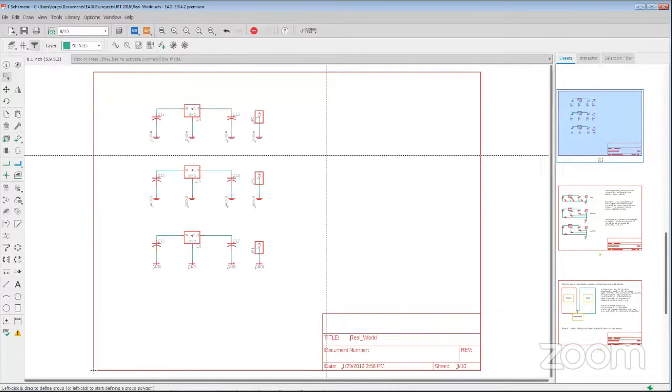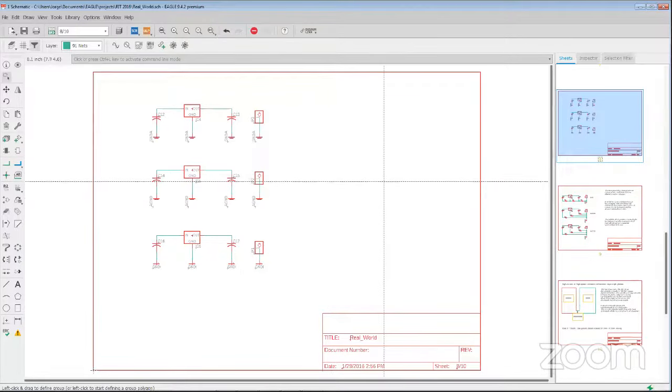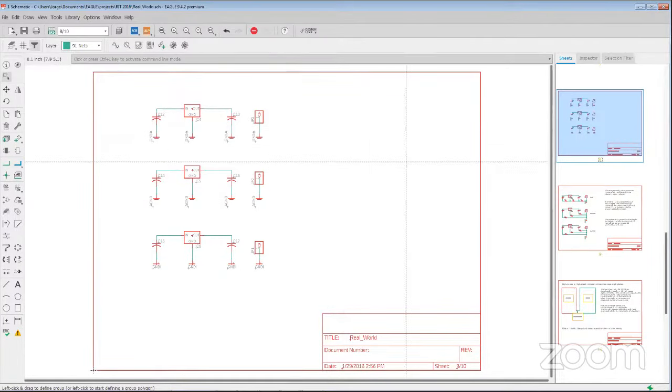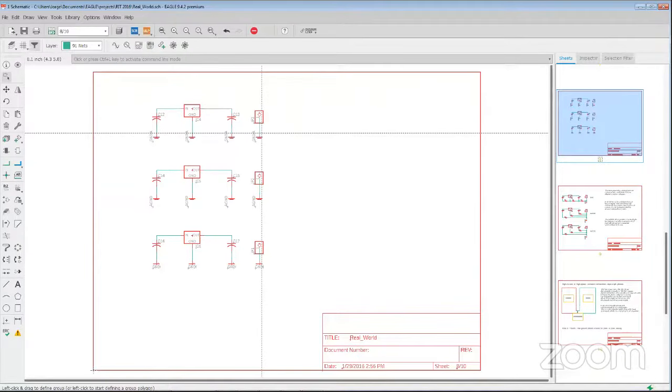When your current flows into a ground plane, it's actually not just dispersing evenly through it. It's actually trying to follow the closest path that it can back to its source under the signal path. In other webinars we'll cover that. But basically in the ground plane, return current tries to be as close as it can to the original signal current, tries to follow the trace from which it came. So with that in mind, let's talk about these different grounding arrangements and why sometimes they can be beneficial or why they can cause difficulties.